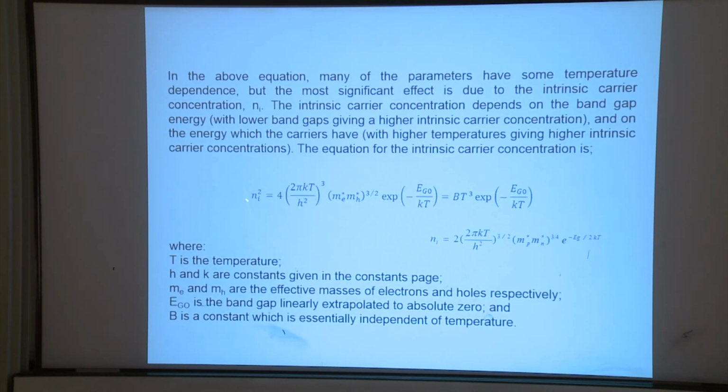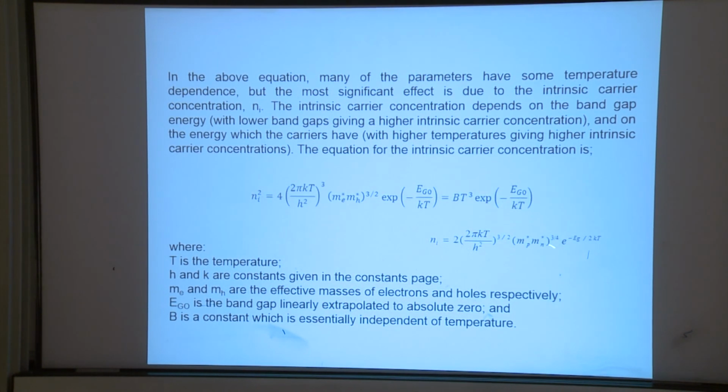Once we know this, and I gave you the equation already, even though I gave it in this form, ni squared you can calculate and rearrange to get this expression. You have to believe me, ni squared can be represented as this. So you can see which terms are related to temperature. This one, right? And this one, right? So we only keep the temperature terms and take the rest as constants, independent of temperature.